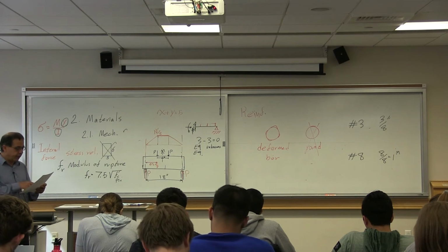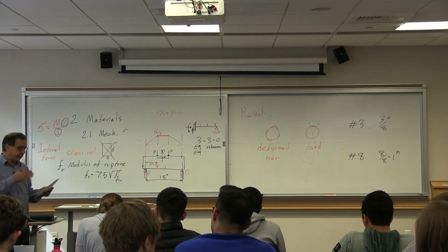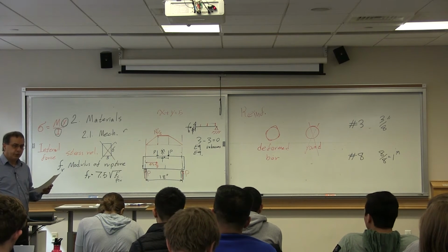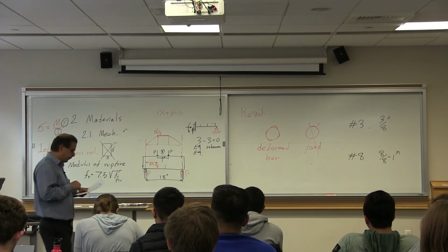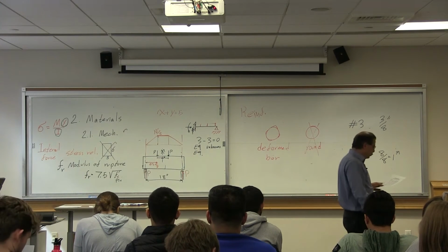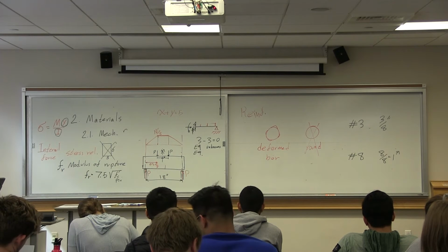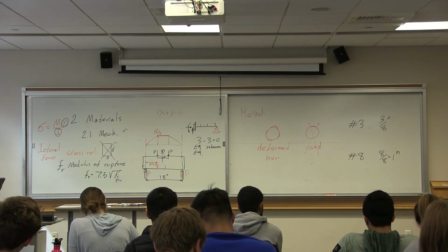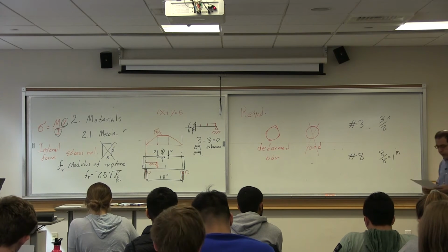If you look at the diameter of number 9, how much is it, the last column? Slightly different, but the reason is if you use 1.128, the area becomes round 1. That's why they changed the diameter slightly to find better numbers.